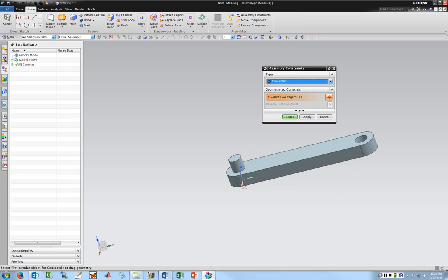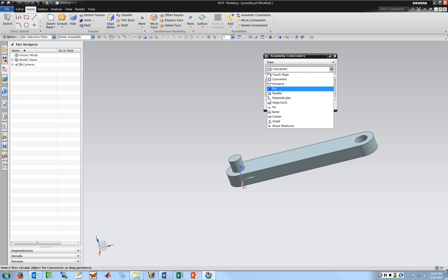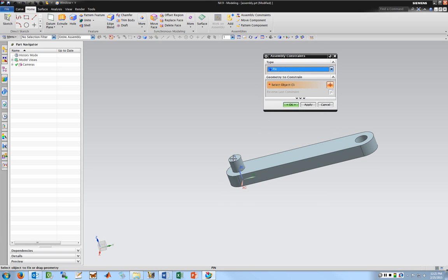So if you want to follow the process I used in the last tutorial, you just add them one at a time. Add the first one, fix it, and then add the next one and use by constraints. Going this way, I definitely need to fix this thing first. Since I used the same coordinates, the x-y plane, for drawing both parts in the same origin, they automatically line up. If they don't line up, you're going to have to either move them around to get the constraints to work, or just apply constraints and see what happens. But since they're where I need them to be, I don't need to try to move them. I'm going to go ahead and fix the pin.